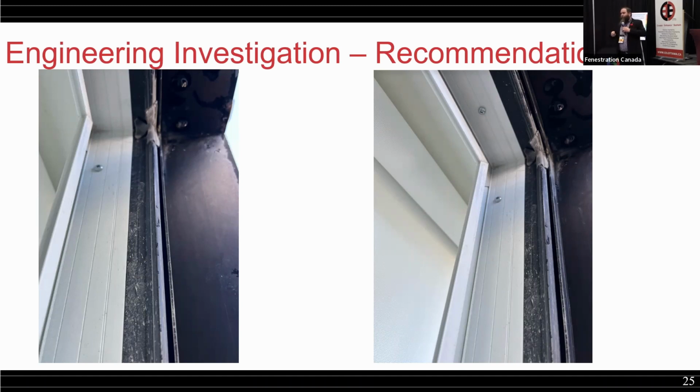When we tested this window, it leaked very slowly. It had caused all sorts of problems. Other teams had already tried to figure it out and couldn't. When we did our method where we go slowly around with our dye penetrant, we found the problem, and we should have found it before we tested the window. I was actually a little ashamed that we hadn't already pointed this out and been like, really? Are you sure?